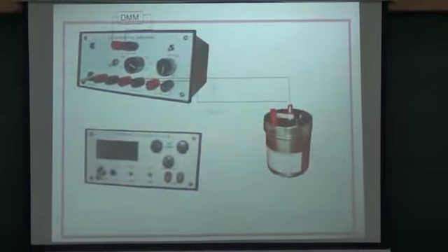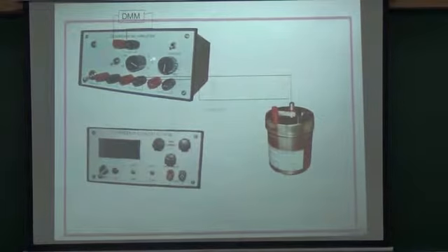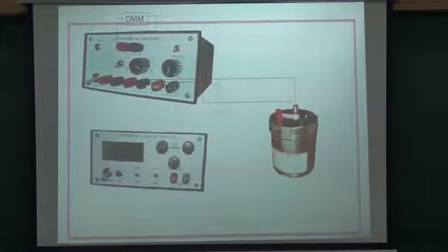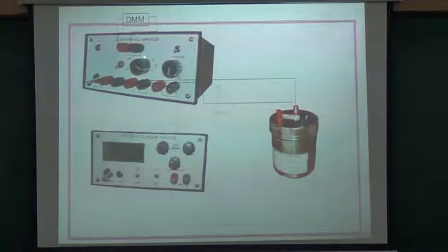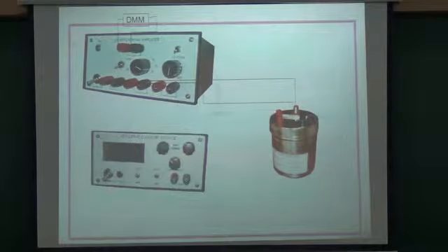Then we connect the 2 thermocouple leads. The output of the thermocouple is connected to one of the 3 terminals, 3 possibilities, of a DC differential amplifier. We select an amplification factor of 100, and the amplified output is measured by a digital multimeter. This is a constant current source. We connect the 2 ends of the constant current source to the heater, and we can set the current.